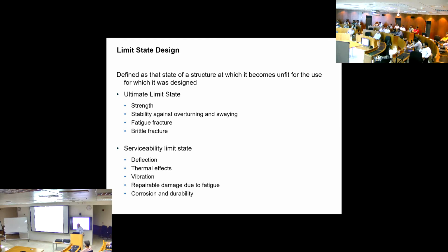So limit state design is when something is designed to its limit. And this goes for the decking and for the upper sheet both, right? Yes, we have both. As a system or each one individually? We can do it for the whole system. So we can do calculations for the deck. There is a load table for the liner, that is the structural side of the liner, and there is a load table for the top sheet, which is two different.